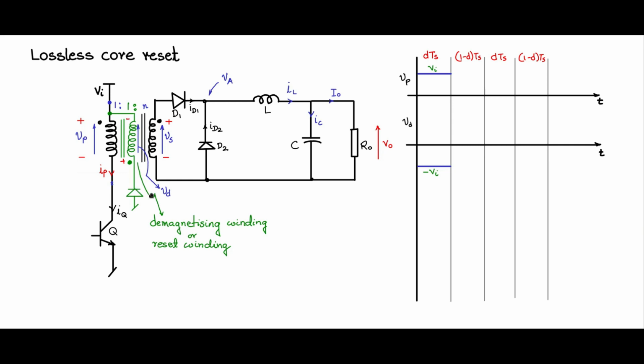But it is also interesting for us to look at what this diode current ID is. So let us also have one axis here for the diode current ID. I would also like to look at the magnetizing part of the IP. I'll come to that later. So the diode current ID, because the diode is reverse biased, will be zero at that moment of time.